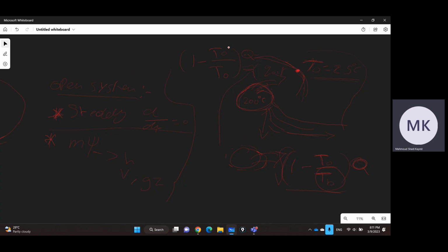So this term is 1 and this whole term will be 0. We will not have any exergy transfer by heat. Instead, this term will appear as an increase in the exergy destroyed, because this heat we didn't utilize, since we are taking our boundary at the environment. We didn't utilize this heat by anything.